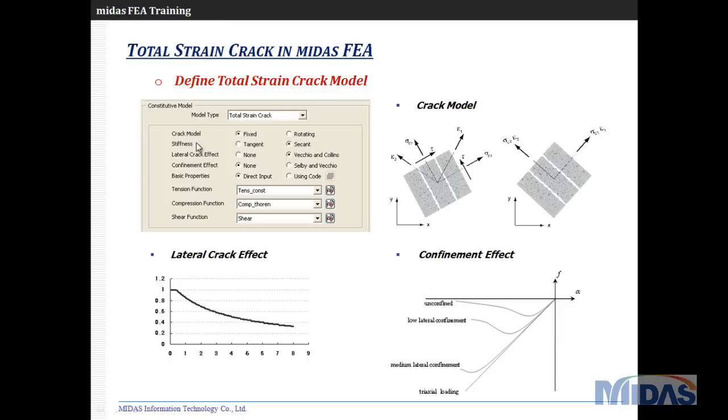So the constitutive model involves the concept of fixed and rotating crack models. The stress and strain relationships are defined by these. The fixed crack model is basically about whether we want to set our crack plane to be fixed, or it has to be rotating. Generally it is the user's choice, depending on the purpose of a simulation or what the real conditions to be simulated are.